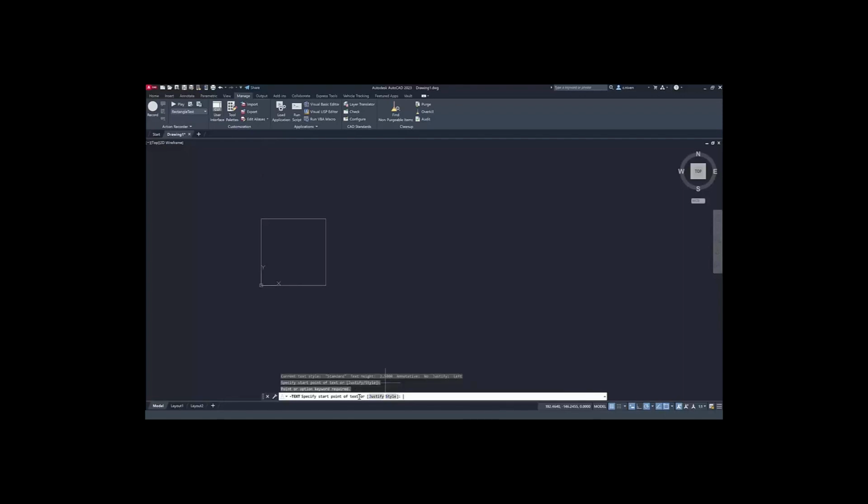And once I know what my series of commands are, I can just put them in order in my AutoCAD file or in my AutoCAD script. So generally, the way I go about creating a script is I have a series of things that I need to do. I will then sit down and figure out what commands and what inputs I need to put into the command line to achieve that. And then from there, I can take that list of commands and inputs and put them into an SCR file. And then when I run that, it should run the same exact series of events.